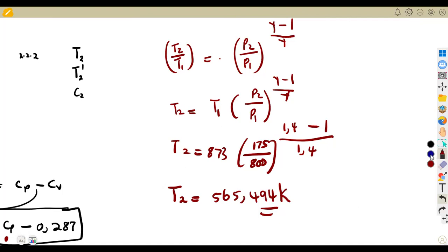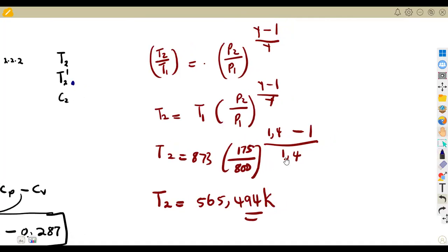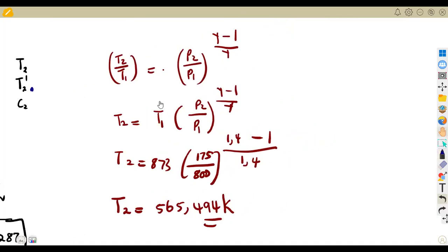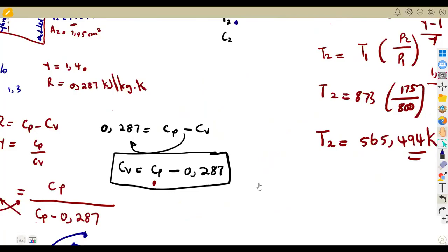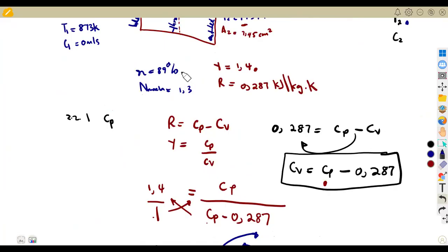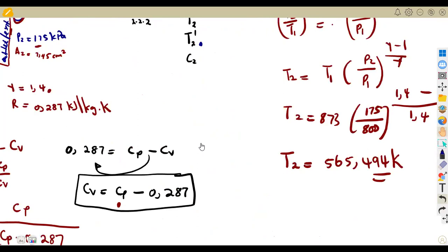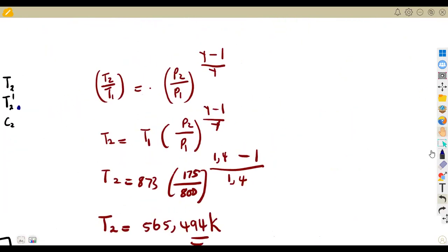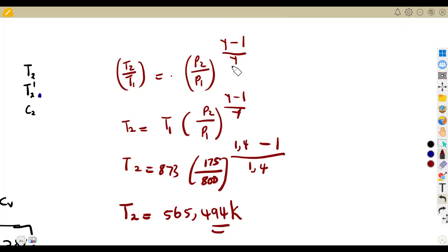Then, all right, we started with the absolute there, which is just like the actual temperature, right? Then we've got the isentropic, this one. For the isentropic now, we do not have a direct formula, but we can take advantage of the efficiency. Remember, I said the efficiency carries actual values and also the isentropic values, and it is the overall efficiency. So you can take that as an advantage. Since we want to calculate T2 bar, all right, we want to calculate T2 bar.